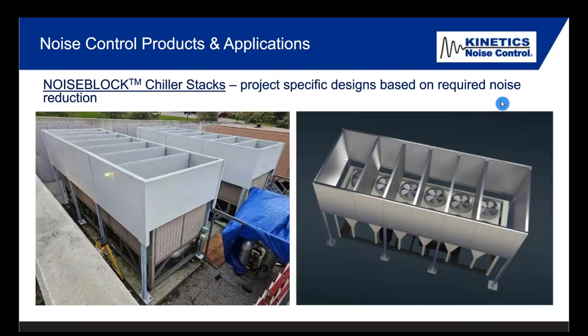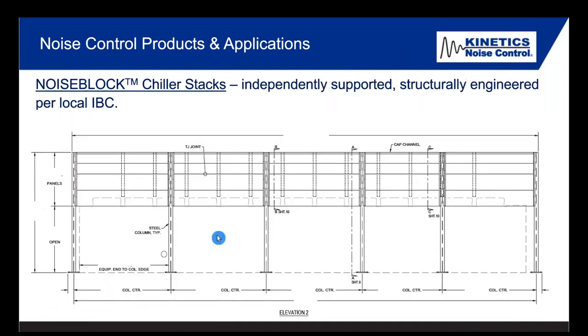We look at air-cooled chillers. Remember we talked about there's 2 types of noise. There's the upblast fans at the top, and there's the compressors at the bottom. And so we want to look at that. And these are chiller stacks. These are all perforated inner shells, perforated baffles, solid outer shell. Comes with optional doors if somebody wants doors to get in. But this shows you equipment yard here with some curtains, but it actually shows these are all structurally designed and PE stamped in-house to meet the local IBC code, and no weight acts upon the unit.